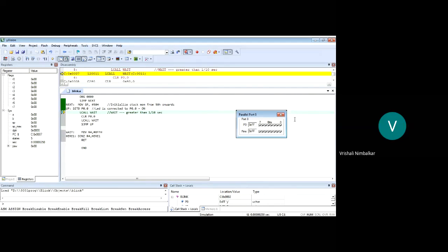Right, and now jump to subroutine. See students, it will jump to wait. Correct, the subroutine jump has happened. Now the first instruction, R4 is loaded with FF. And now it keeps on decrementing R4, FE and so on. I'm just pressing it.